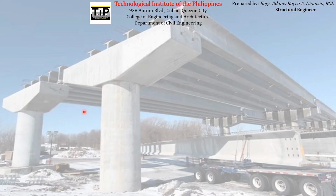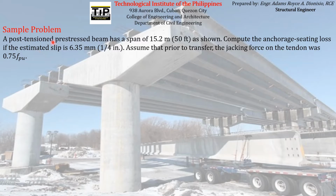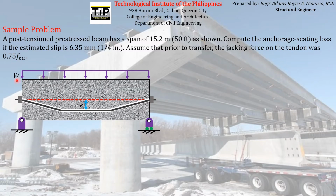So to better understand the computation for the pre-stress loss due to anchorage seating, let us apply it in a sample problem. So a post-tension pre-stress beam has a span of 15.2 meters or 50 feet as shown. So this is the post-tension pre-stress beam. So it is actually a simply supported beam which supports a uniformly distributed load W and has a harp tendon